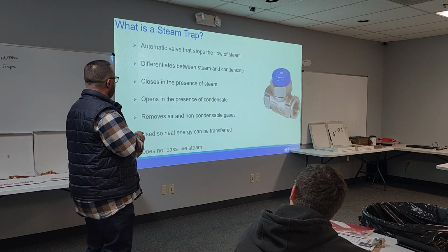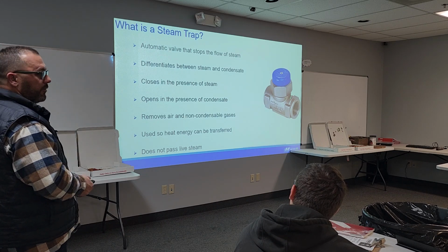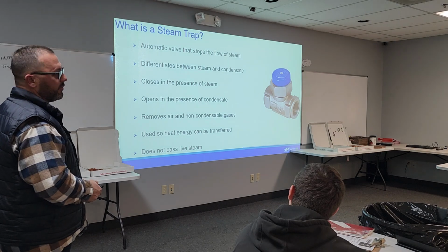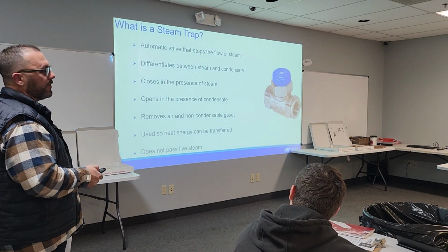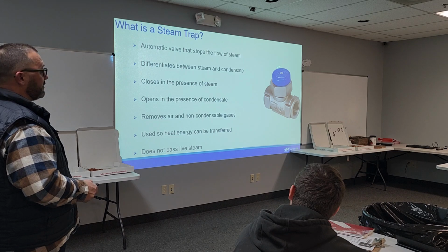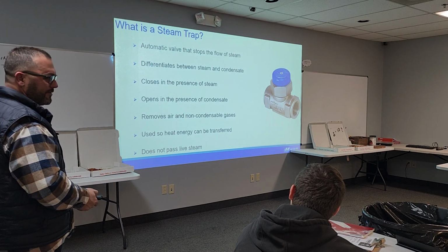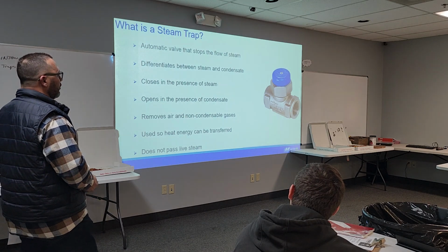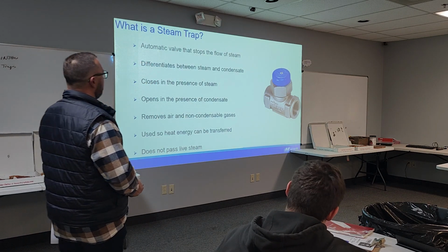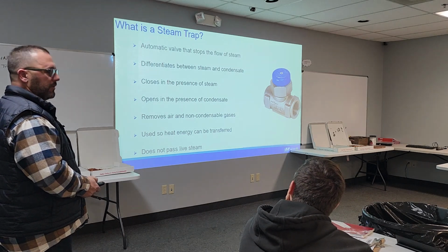These traps, thermodynamic, TD traps, they don't do very well with air. These are the ones that I said, below 30 psi, they don't work very well at all. You start getting below 20, you get into 15 and 10. I've seen them used, and people say, yeah, they're fine. Like, hey, do you have any problems with that? No, it's fine. Well, they don't work very well. Yeah, they don't work very well. You sit on a rusty nail long enough, you get used to that too.